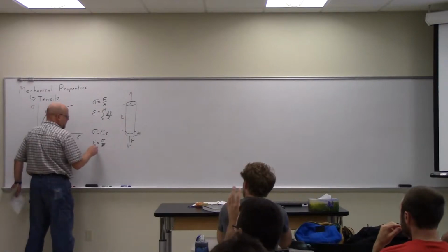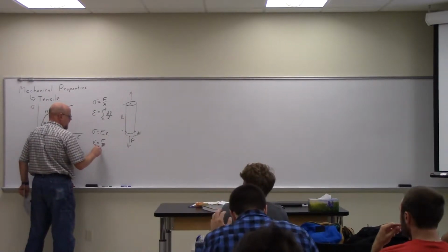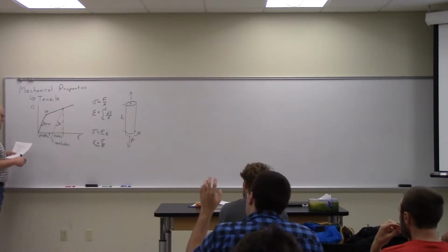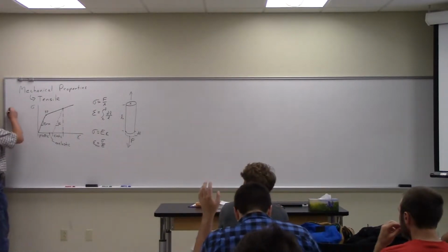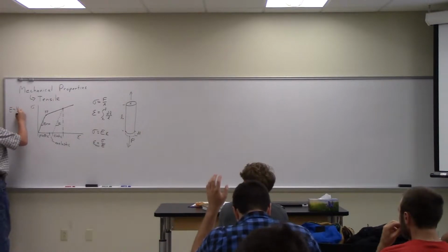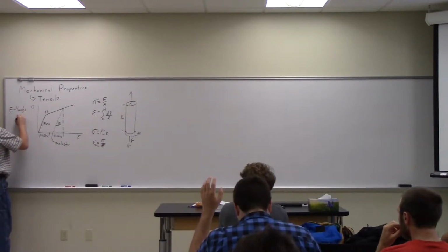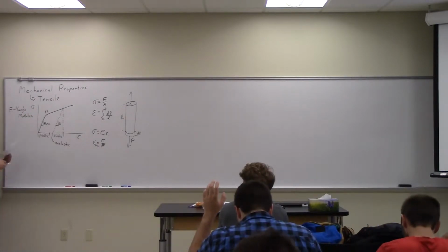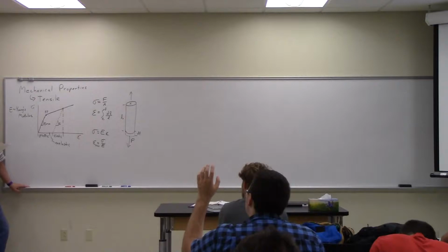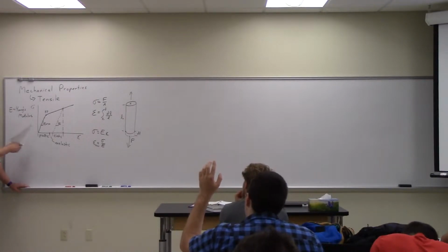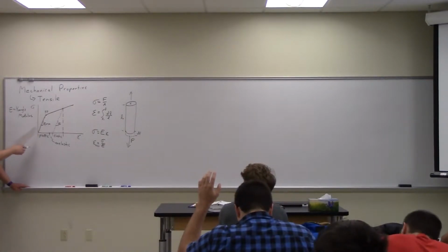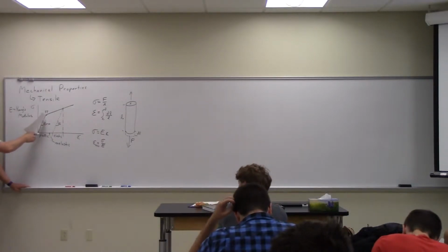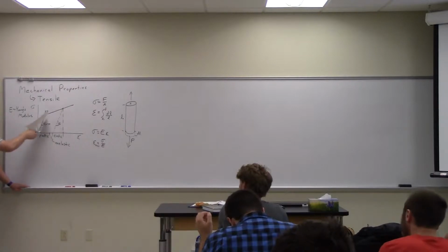So the elastic portion will be the stress divided by the modulus. E is called Young's modulus, or sometimes just the elastic modulus. So that behaves according to Hooke's law. Remember Hooke's law from springs, F = kx. It behaves according to Hooke's law in here, and anytime it relaxes, this part is the deformation.